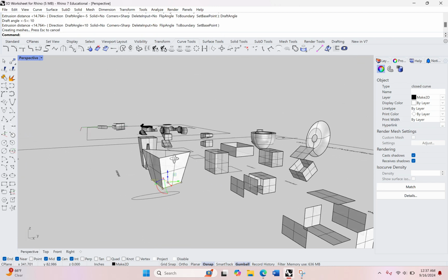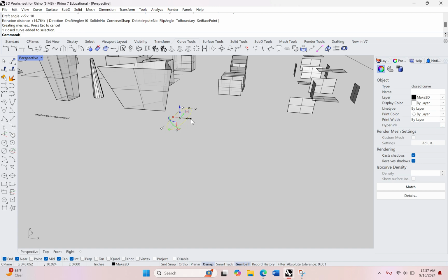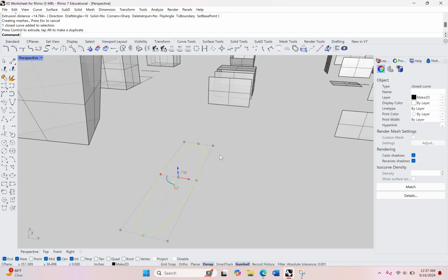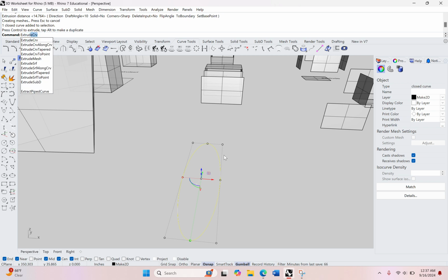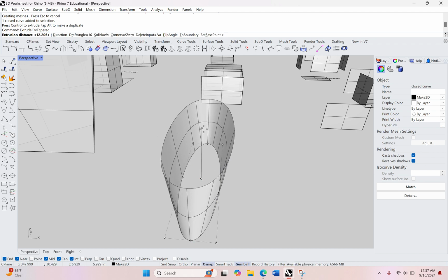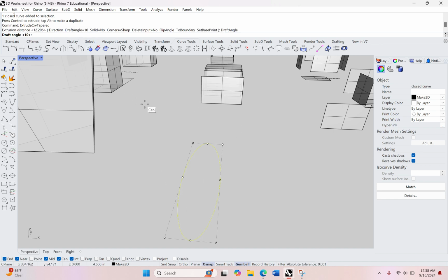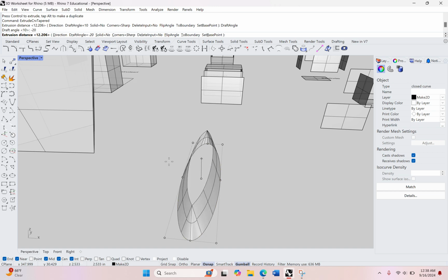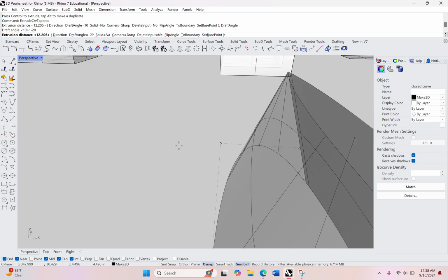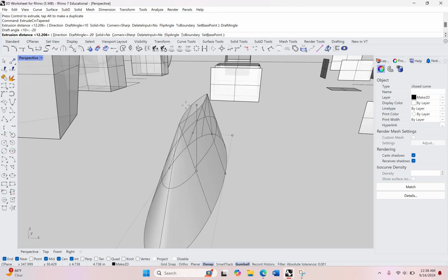Let's look at this. Okay. All right, let's do something a little different with the ellipse. Bring it out this way. Once again, extrude CRV tapered. And whereas with the triangle I did a positive number, for the draft angle, let's do -20 and just kind of see. All right. We run into some funny issues here. Nothing we can't figure out. It's pretty interesting.